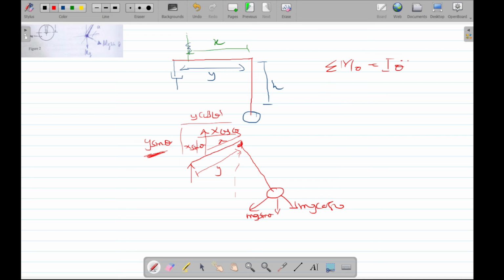So the coefficient first, c. Now we assume that the direction for the movement of the body itself is positive. The body is rotating in this direction, so every moment that goes this way will become negative. Now the damper is moving up, the spring is moving up, the weight is going this way. So they are going to be negative.